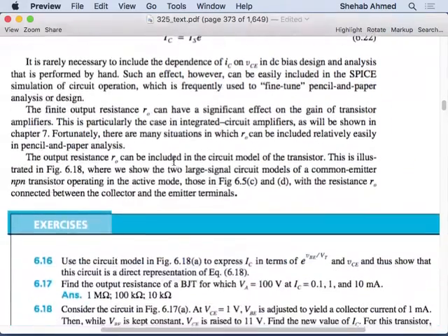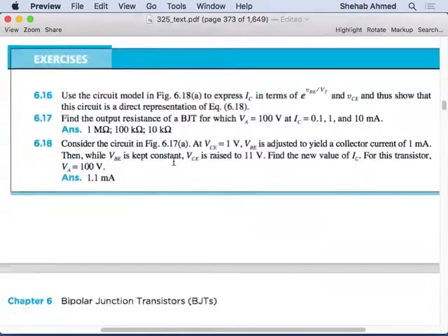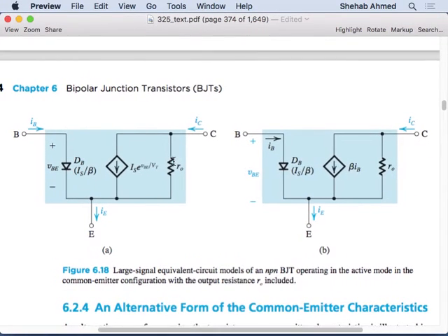That's the conclusion here. But again, like we did for the channel length modulation and many of the problems, from a design perspective, we will initially maybe ignore that. Because typically you design a circuit, and then you will simulate it. Typically in simulation, you will simulate maybe two levels. You will simulate with an ideal device, and then maybe simulate with the actual device, including the early voltage effect and the slope on the current.